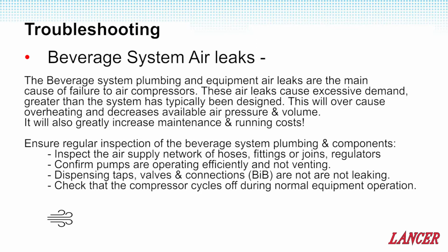Inspect air supply network hoses and fittings, joints, regulators. Confirm pumps are operating efficiently and effectively. Check that dispensing taps and valves, bib connections are not leaking, and then ensure that the compressor actually cycles off during normal equipment operation.